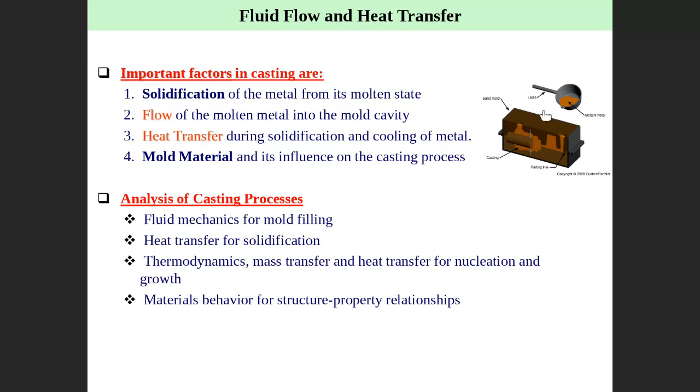If you manufacture the mold here made of metal, for example, as a permanent cast, the heat transfer rate and cooling rate will be very high. Solidification will happen quickly, and you have to consider that when you design the mold, right?